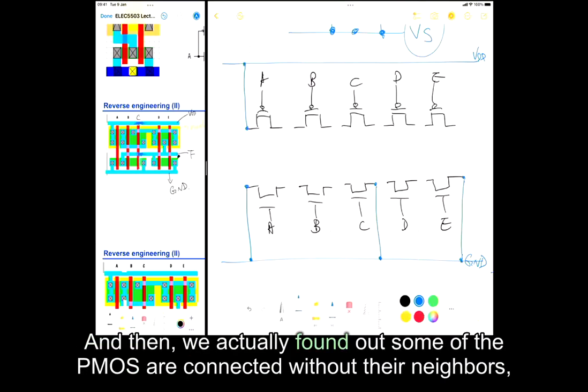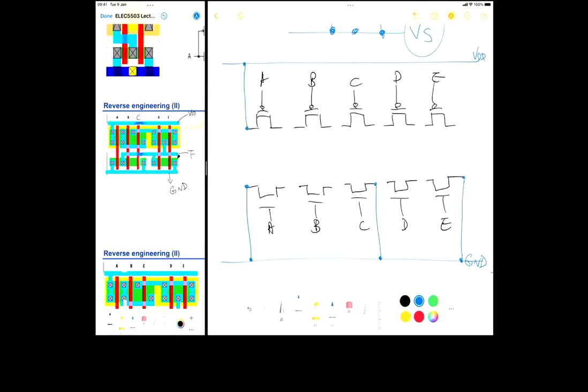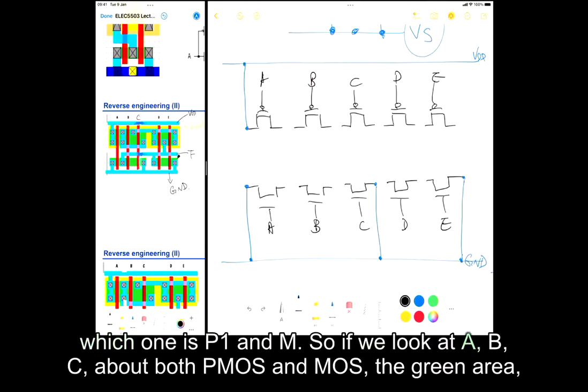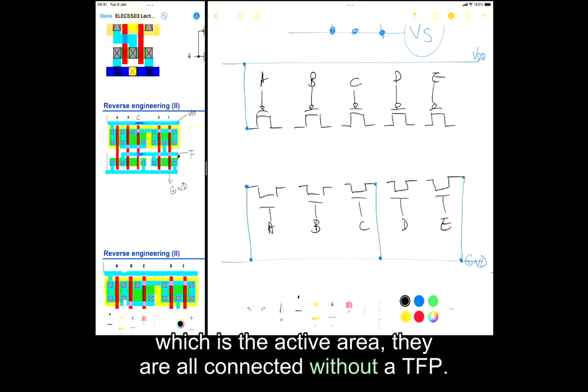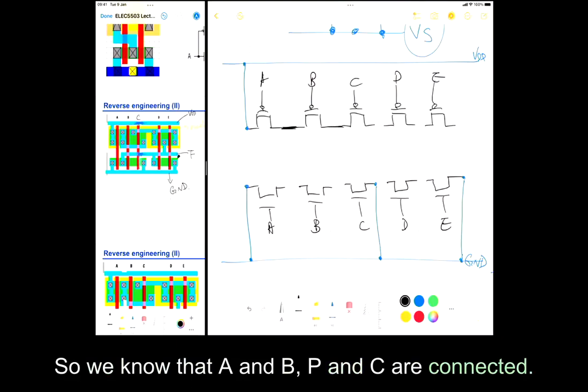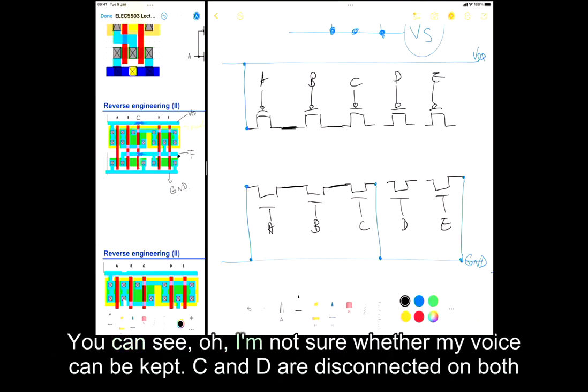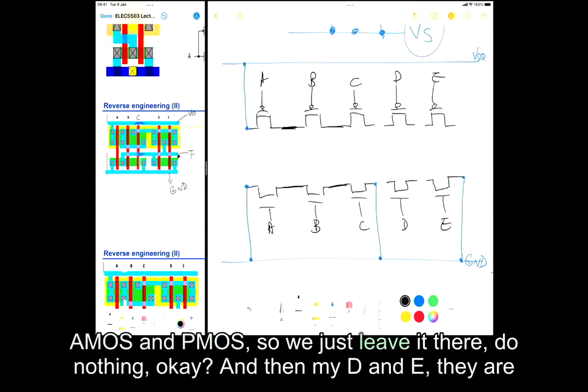And then we actually found out some of the PMOS are connected with their neighbors and some are disconnected. That's why for these ones, I left a gap here for my P1 and N. So we'll see which one is joined, which one is not. If we look at ABC of both PMOS and NMOS, the green area, which is the active area, they are all connected without a gap. So we know that A and B, B and C are connected. Same for my NMOS. A and B, B and C are connected. But C and D are not. They're disconnected, right? C and D are disconnected on both NMOS and PMOS, so we just leave it there, do nothing, okay? And then my D and E, they're connected, so I connect them.